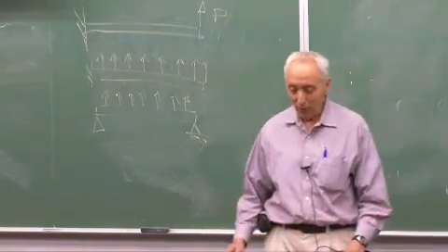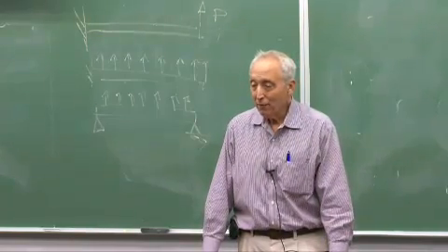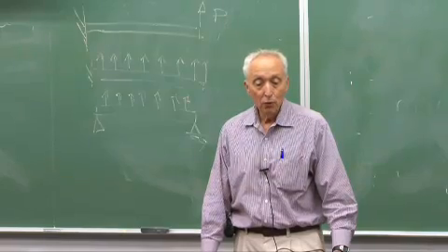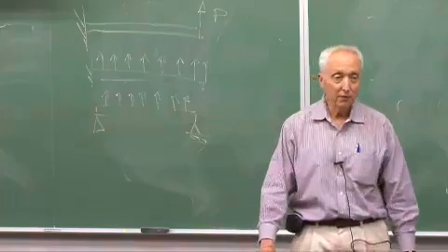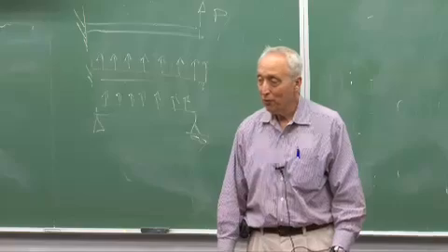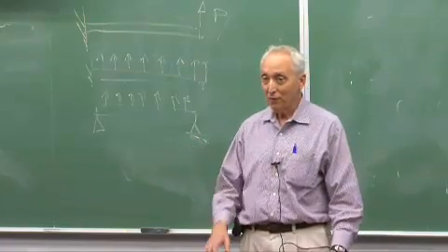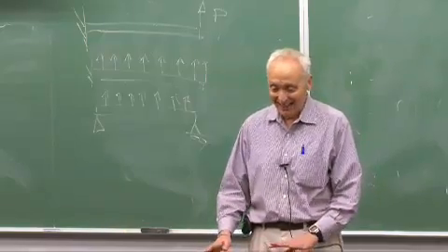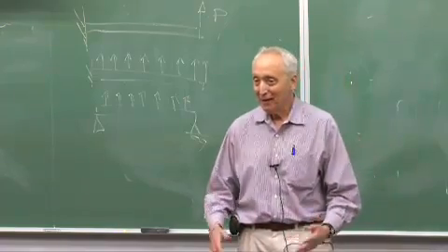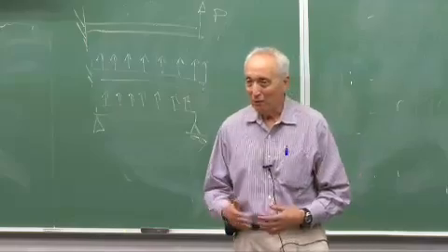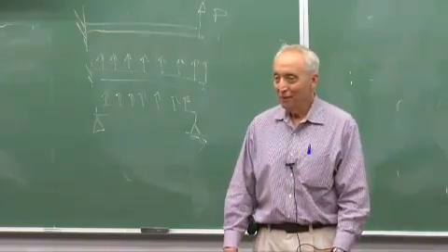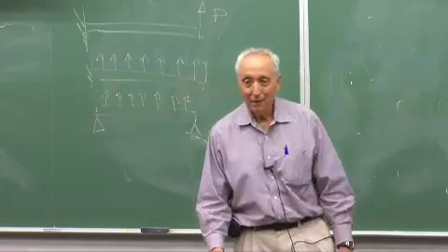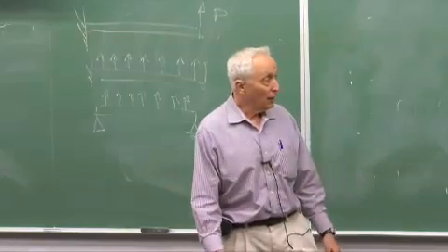I didn't run into more than one or two in my career, but one example was that in finite element analysis, people have used Gauss integration in order to calculate stiffness matrix, and then they noticed that the order of convergence of the stresses at those Gauss points was better than expected, and somebody worked very hard to show that it should happen. That is, you stumble across a way of wringing more accuracy from your code than you thought possible, so you go and prove that that's the way it should be. And what people do now is that they take advantage of that.